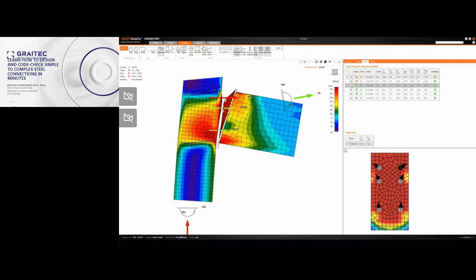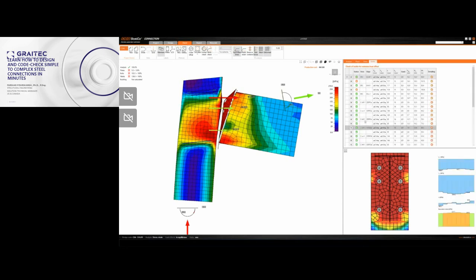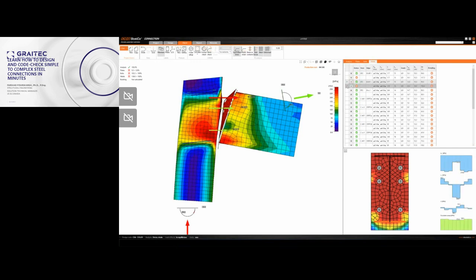And finally, we have the results for welds. So if I click there, it's going to be the new table here. And here you can just select and go through the welds and see the stress distribution, shear, perpendicular, parallel stress, etc. on the lengths of the weld. So here, for example, I can just select there. This weld that I've selected is going to be highlighted by orange. And here I can see the stress distribution along the weld, which is happening on that weld.